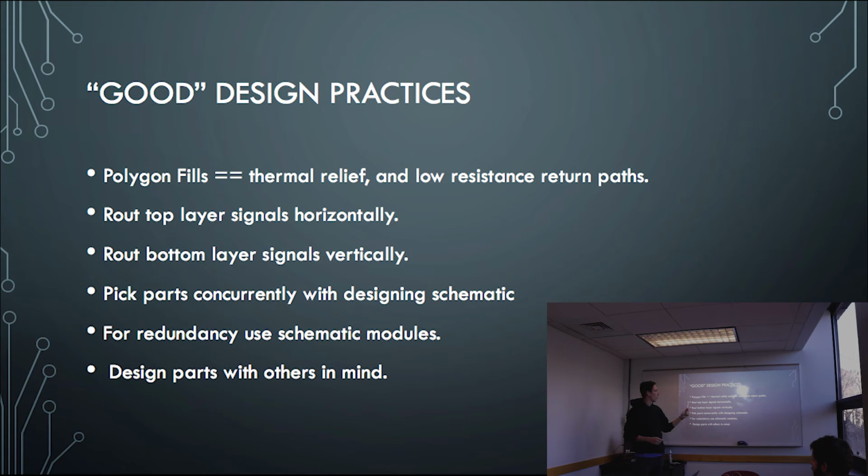And usually what I do, if you're having any problems with thermal relief underneath any IC or anything, is a polygon and small little vias will cure that. For anything else, you probably need a heat sink.